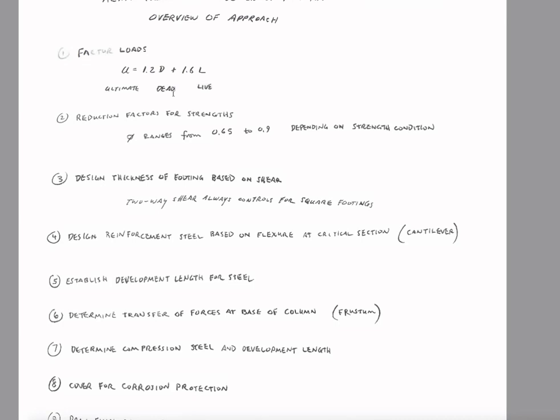But there would be some standards that you could apply to this and get some estimates. But in any event, you will have, in the end, dead load that you'd be working with. And that would be the material that stays in place. And this will be a lower factor that's applied because it is quite certain what that will be.